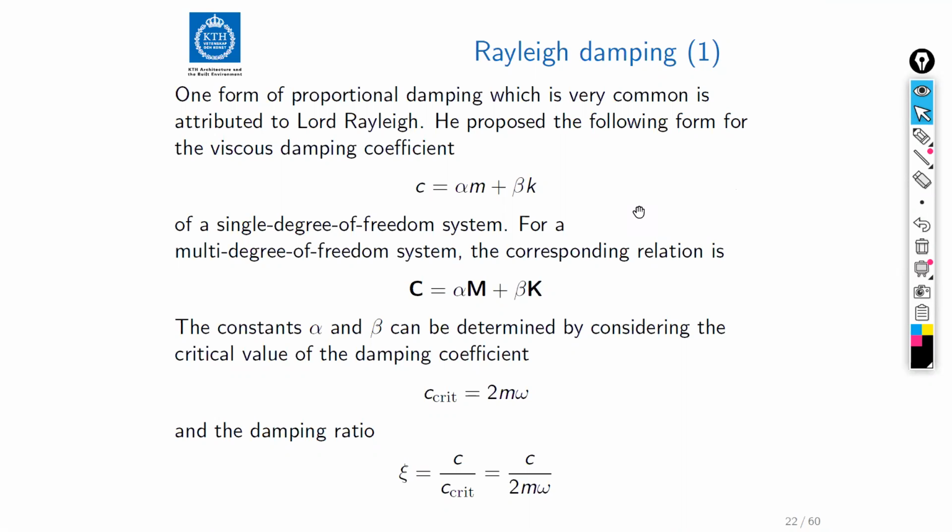We were talking about ways of defining the damping matrix for solving structural dynamics problems using the finite element method. We made some historical notion of Lord Rayleigh and his idea about combining the mass and stiffness properties of the system to define a damping coefficient. And then we wanted to generalize this to a multi-degree of freedom system. And I claim that we can do this in the straightforward way of simply replacing the model parameters' scalar values with their corresponding matrix values like this.